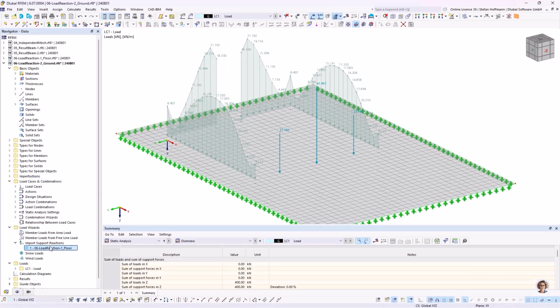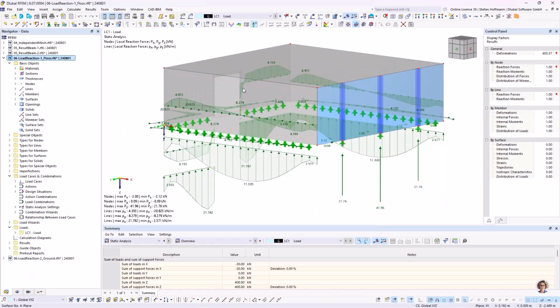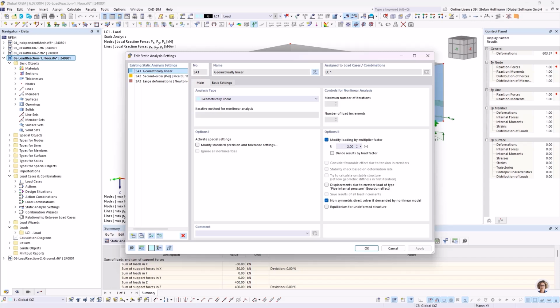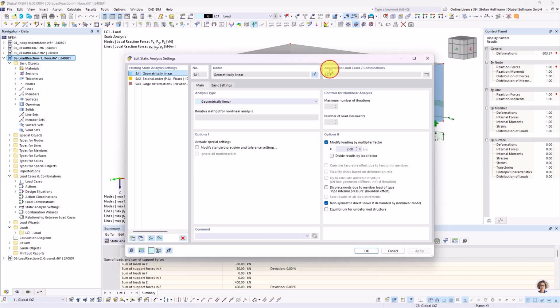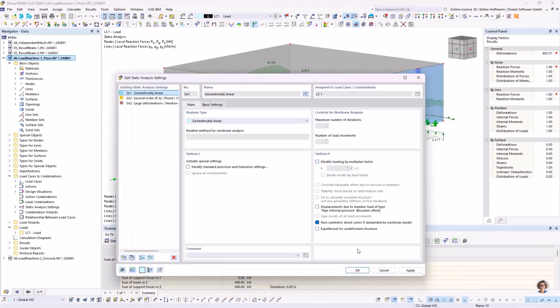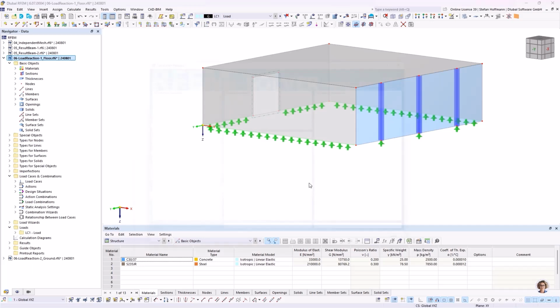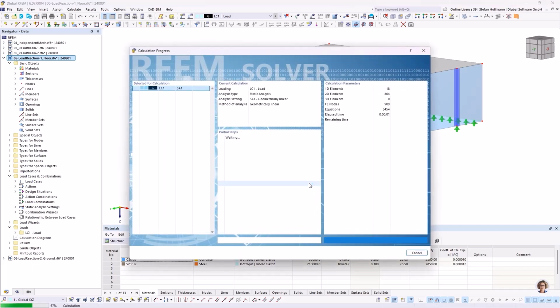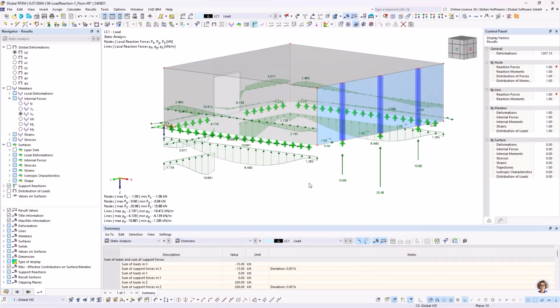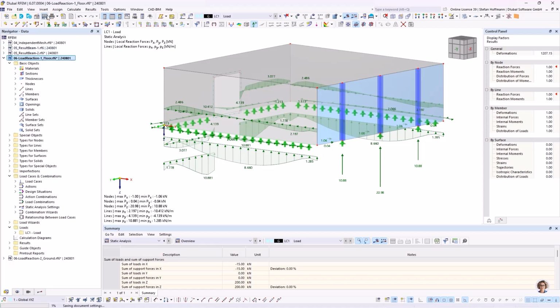Now the highest functionality increase, I think, once we have these 3 loads, is that once you go into the floor and, for example, double the forces, which can be done in the static analysis settings, I see I've already introduced this, and now we will just lower it by a half. If we do not modify it, let's have a look, 42 kilonewton in the Z direction. If we disable it and hit F5, you always have to think that this model was not yet saved, so nothing is told to the floor below. And if we hit save, there should be a warning that the results will be deleted.